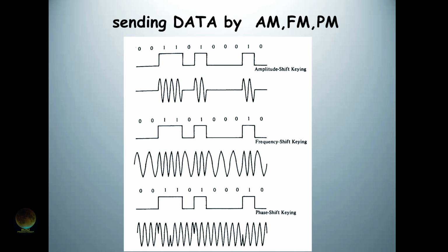I'm not changing the frequency. I'm not changing the phase. I'm just changing the amplitude. My frequency is fixed. Though typically, we say that's like CW. Frequency shift. Well, that's the RTTY. Zeros are one frequency, okay, and the ones are a different frequency. Notice here, the amplitude's constant, right? But also notice, hey, wait a minute, the radio's never off.